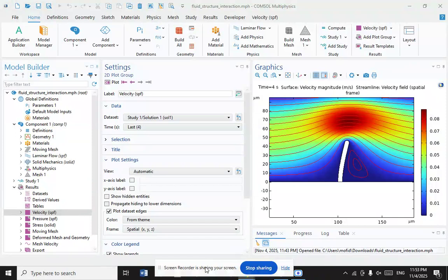While fluid structure interaction offers better analysis, it comes at a cost of highly increased computational time. Non-compliant models have a computational time of a few hours, while fluid structure interaction models could take up to 7 days to finish running. This makes fluid structure interaction models most useful for preventative measures for a vessel caught early, but unusable for emergency situations where the vessel may have already ruptured.